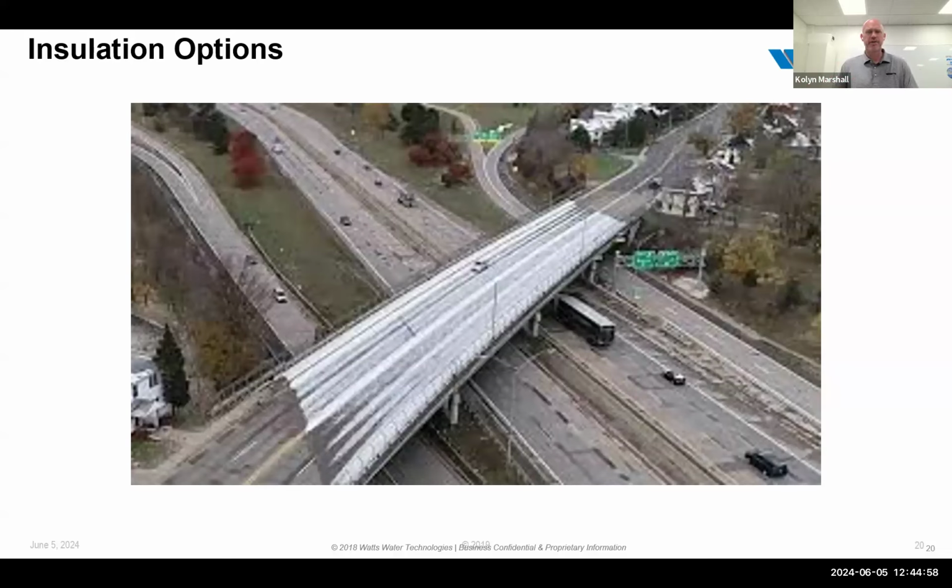Why is that important? It's important because of residual water. When we melt snow, we create water, and that water flows somewhere. It's going to maybe flow off the side. It's going to flow downhill. We got to have a way to remove the water from the snowmelt area. If we shut off the snowmelt system and it cools too quickly, that residual water has the potential to turn into black ice. And we actually end up creating a hazard that we were actually trying to avoid.